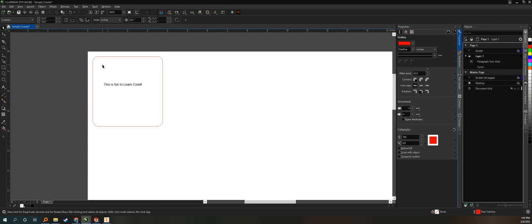What does that mean? Well, there's basically three ways to engrave. We can have a through-cut line, we can have a vector etched line, and an engraving. Now the through-cut line will cut all the way through your material. If I have a giant board of 1/4 inch birch ply, then it's going to cut all the way through. That's a hairline thickness. It's going to be red. If I want to just have a hairline thickness line, but just etched on the very top, that's going to be blue. And if I want to have any sort of engraving, anything with a thickness is going to be black, and that'll engrave into the material.